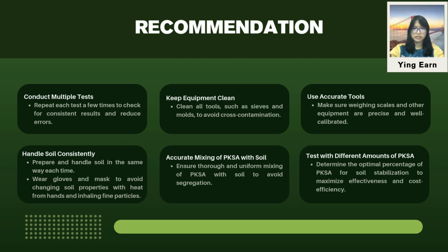Finally, we should conduct the test with different amounts of PKSA. For example, we can add 2%, 4%, or 8% of PKSA into the soil, and then compare the results, and therefore we can determine the optimal percentage of PKSA for effective soil stabilization and also cost efficiency.